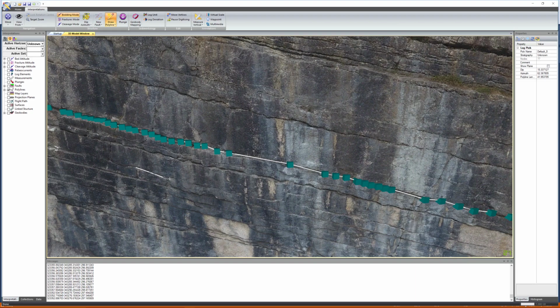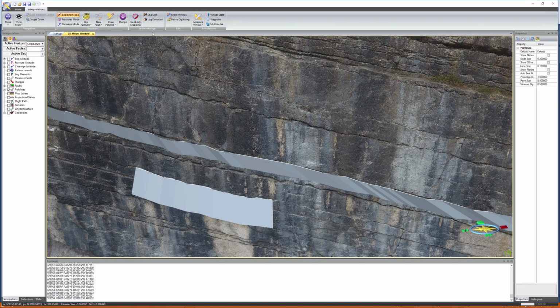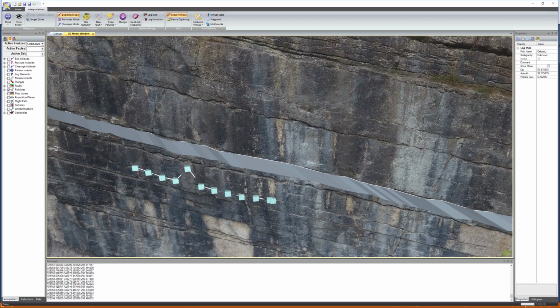We're drawing our polylines. We've got a minimum digitizer spacing of half a meter at the moment. Double click to finish. Select the line. We see the vertices we've got in the polyline. We can then go to Move Vertices, click on a vertex, and then move them to wherever we want.